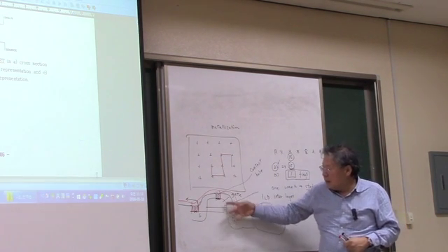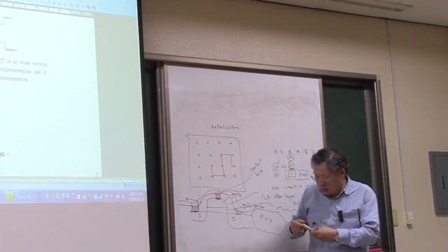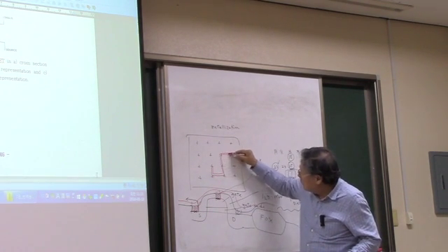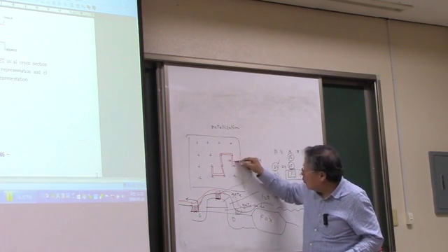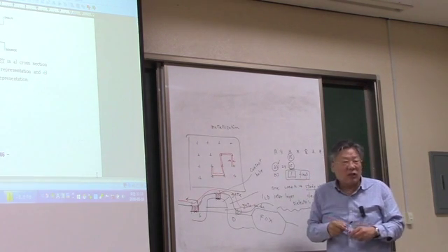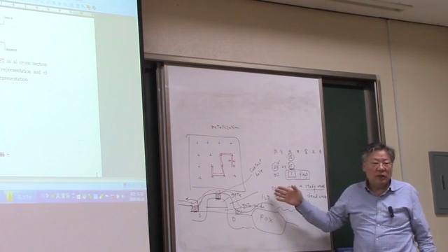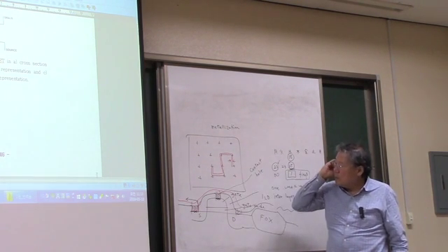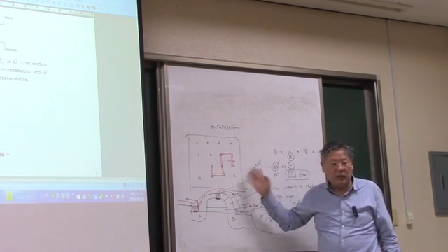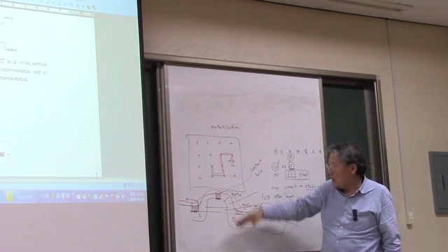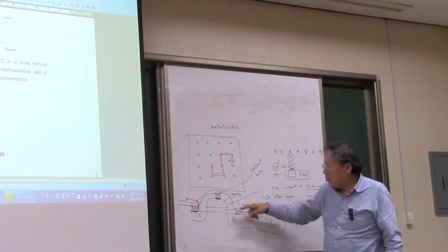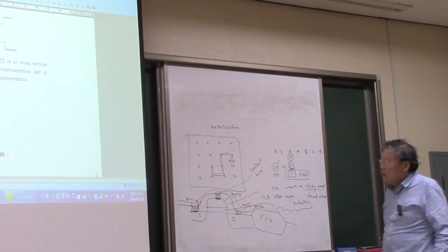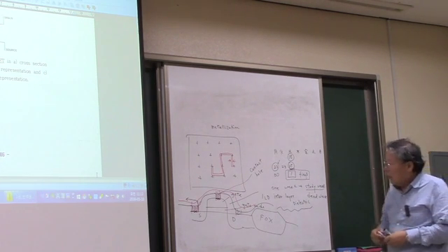And the dimensions we are talking about, the metal line width, is not that critical at this stage. Okay, so we usually use the wet etching process for the metal etch and finalize the interconnection of the transistors.